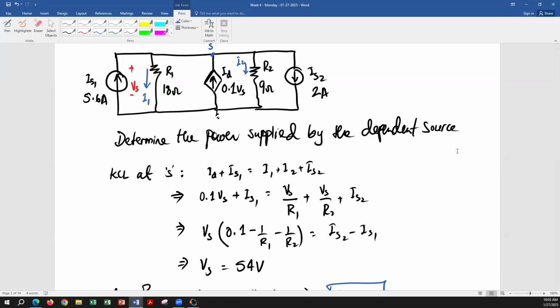Once you have that goal set up, once you're very clear this is what I'm looking for, because if I do this, I'm going to get my results based on that, then you think about how you're going to get that goal and what you're going to use. Start with Ohm's law, because that's the easiest thing. If the problem can be solved using Ohm's law, you don't need to go further, right? You just apply Ohm's law. That's the basic thing. If it cannot be solved using Ohm's law, then go to KCL, apply nodal if necessary, KVL, apply mesh if necessary, source combination, whatever. But don't forget the basic thing: if you can do Ohm's law, go for that always.